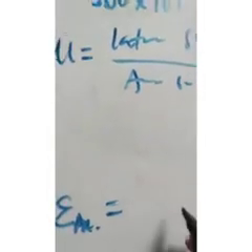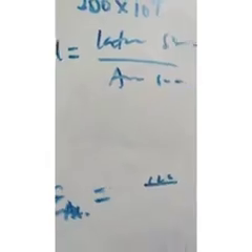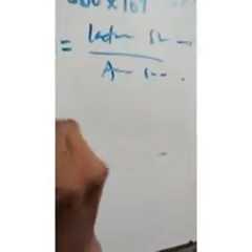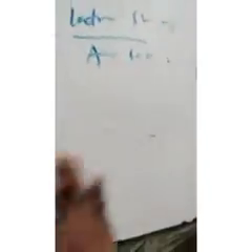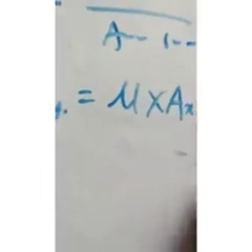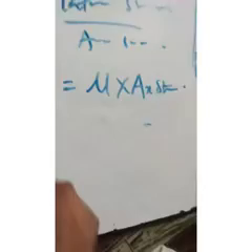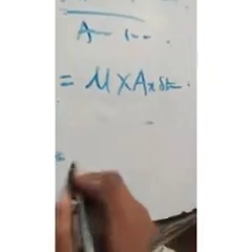But in this context, my lateral strain is what I'm looking for. So my axial strain is this. I come again. The axial strain is that which tends to act like this. Okay, the axial part. So I say we should shorten it like this, and I can have my axial strain, that is this guy here, to now be equal to... my lateral strain. The lateral strain will now be equal to my Poisson ratio times axial strain. Okay, so from this context I can have my lateral strain.